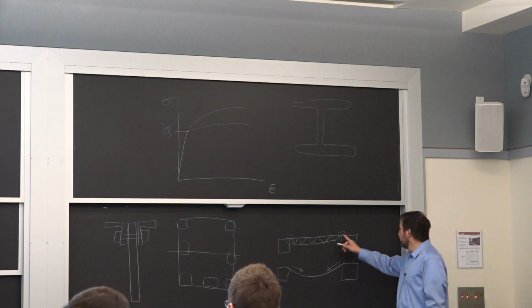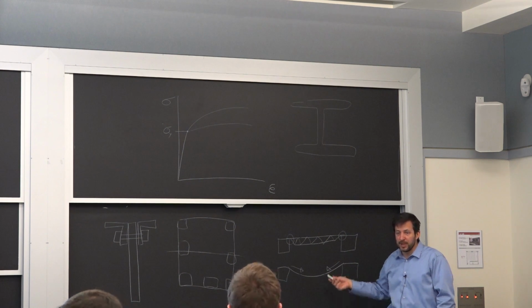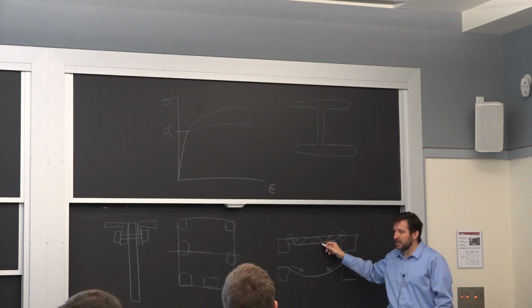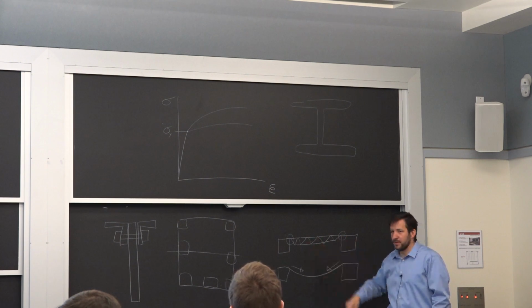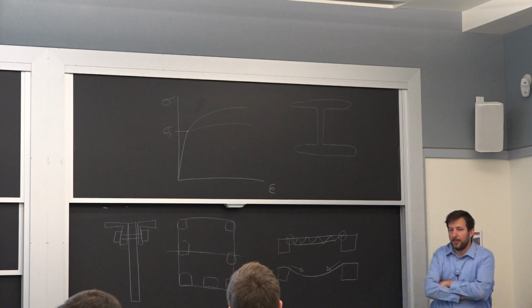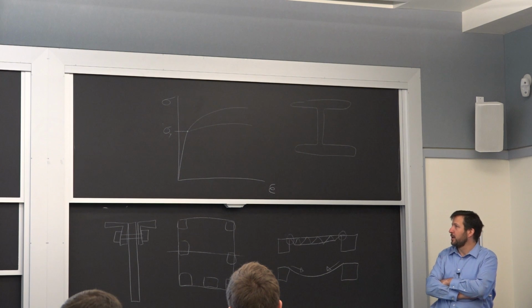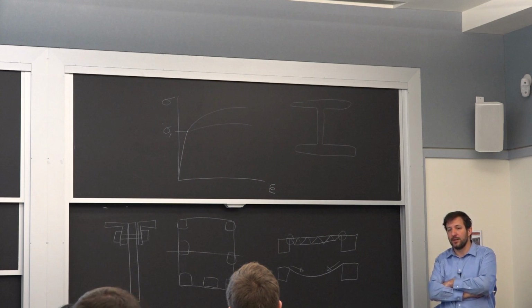One of them is you can say these connections are just going to give up if there is heating and softening. So you make them weaker, and there's one floor that comes out. Okay, big deal. That's one solution. The other solution is to not really have these thin steel members that are uninsulated.